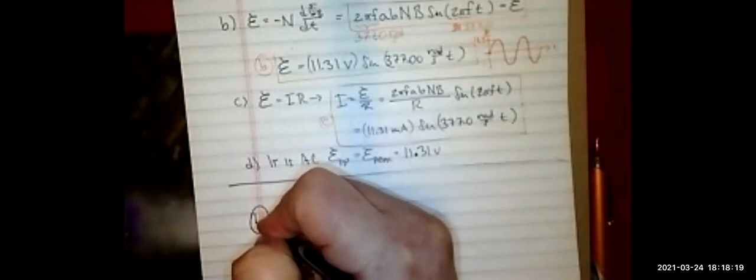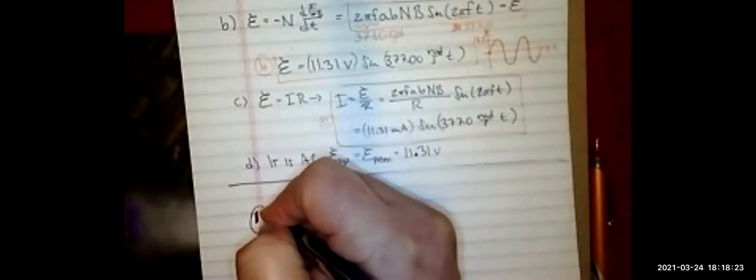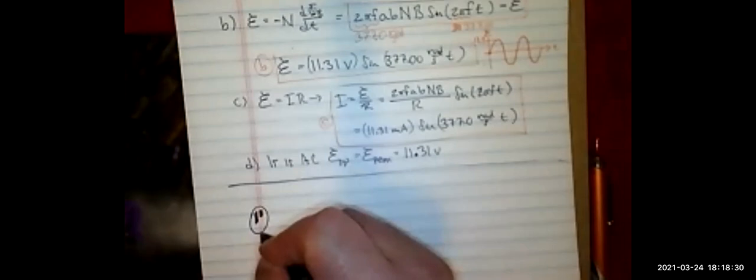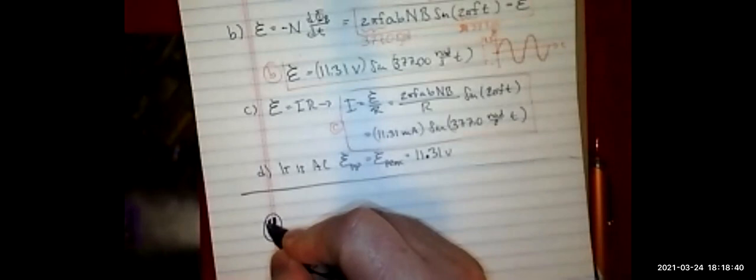That little receptacle has one long slit, and then it has a short slit, and it has a little mouth down here. Okay. When you wire this up, and I always have to check to make sure, so don't hold me on this, but generally speaking, I seem to recall the big one is the black wire, the little one is the white wire, and of course this one I know is the ground. So that's the way that works.